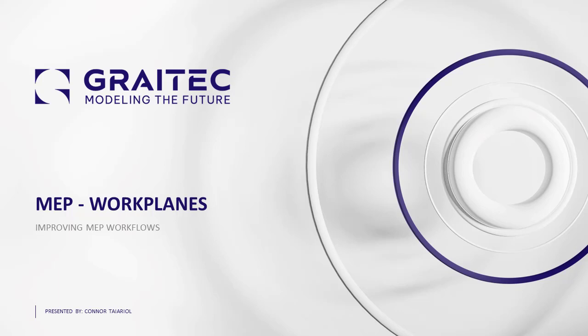be in a linked file in a typical MEP workflow. If that linked wall or ceiling gets deleted by the architect, then those elements would also be deleted. So this is why we would place elements onto a workplane.